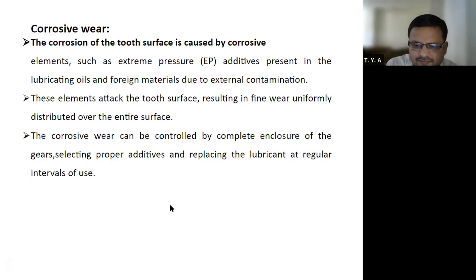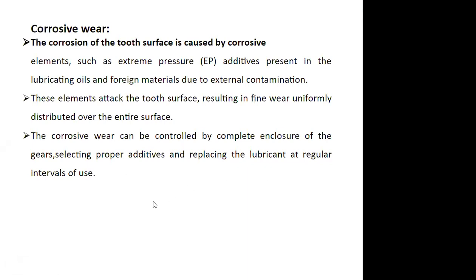The corrosive wear can be controlled by complete enclosure of the gears, selecting proper additives, and replacing the lubricant at regular intervals of use.